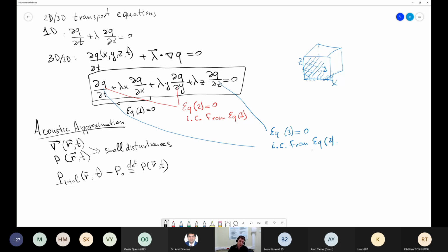What parameters we have to use to describe the dynamic behavior of fluid under the pressure? Of course, we have material with some density, and something like bulk compression modulus or some other constant that relates the strain and stresses. I will introduce here C as the speed of the propagation of pressure waves, of P waves inside this, but you can easily calculate that C is equal to the square root of K, the compression modulus, divided by rho.